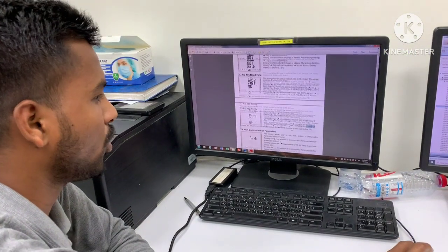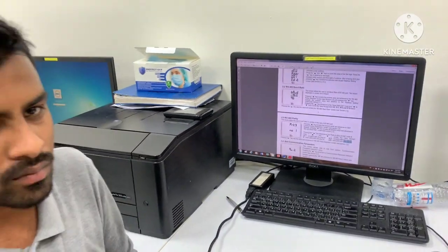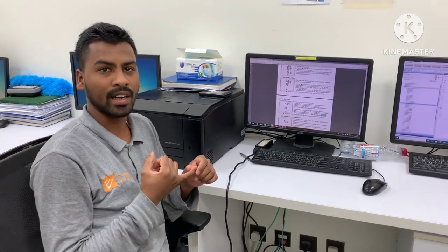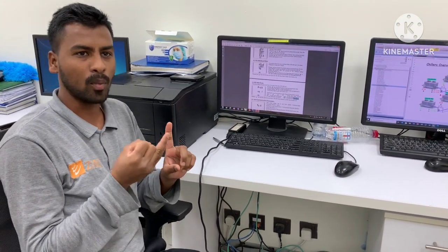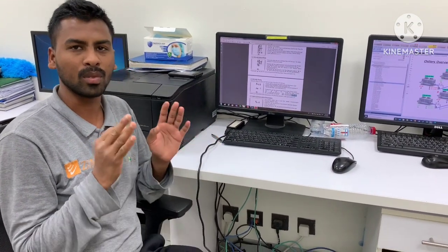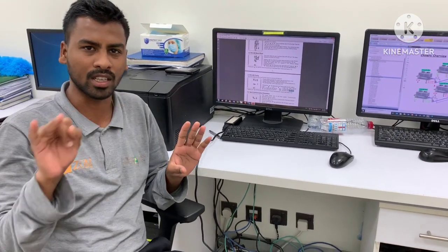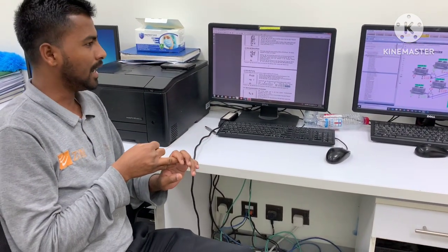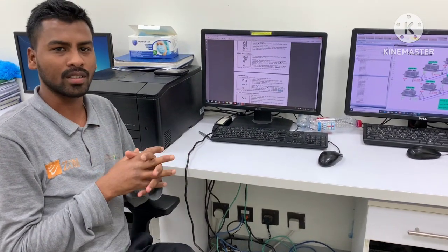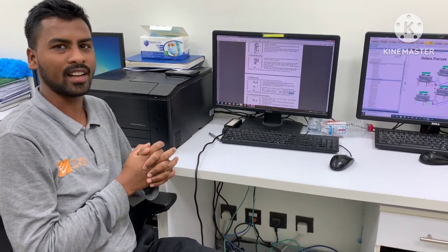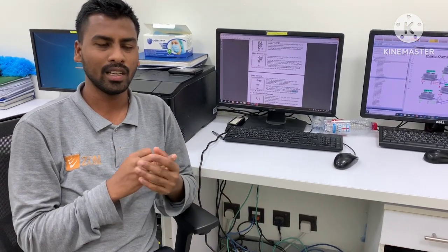Okay. So mainly you have to set the group addresses, unique addresses for each Modbus device first, and the second thing, the baud rate for a network must be the same for all the devices connected to that same network. And very importantly, you must have the documentation for the register addressing for each parameter.